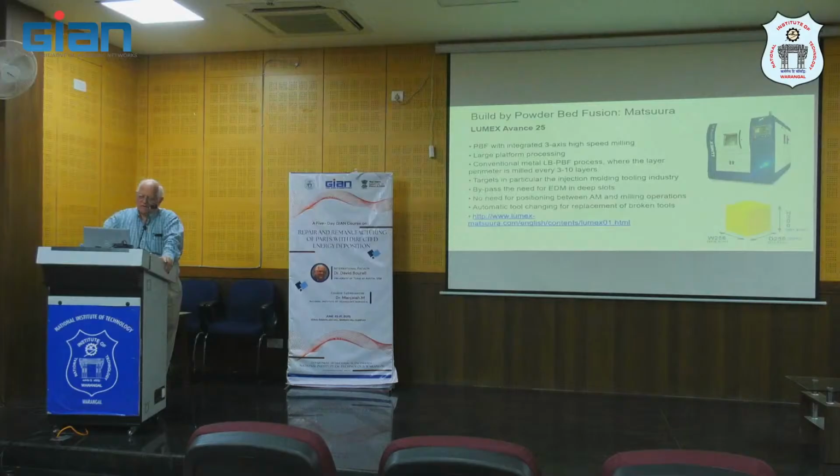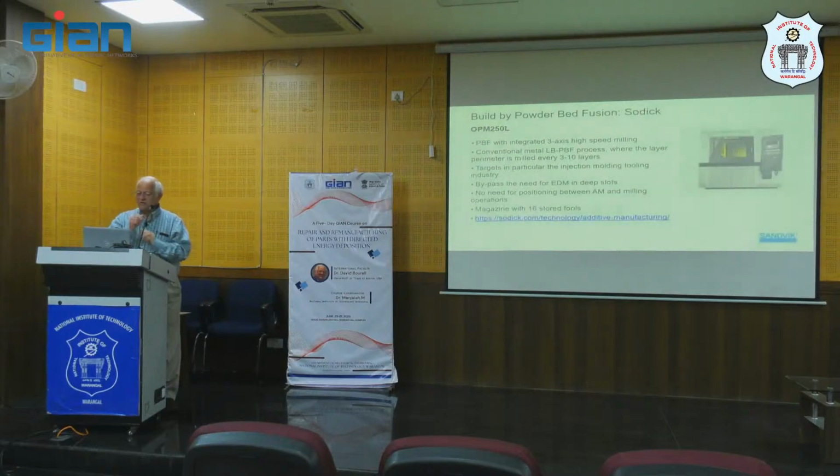Yeah, and again, the main purpose was to bypass having to electro discharge machine the deep slots. And again, no need for positioning between the additive and the milling operations. So that's a big deal. And it's, again, an automatic tool changing and a replacement of broken tools.